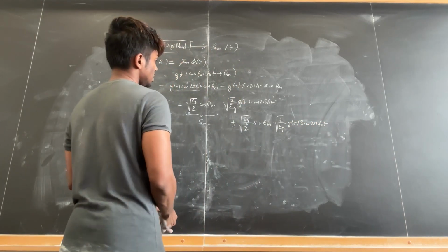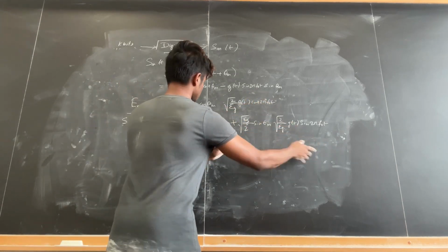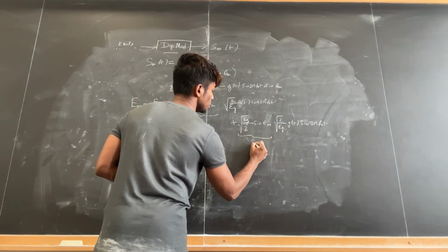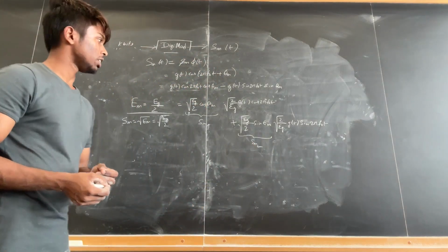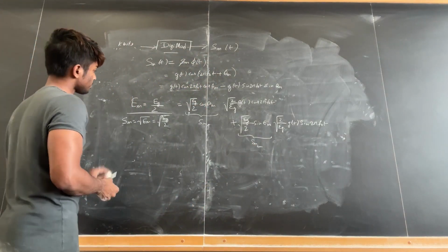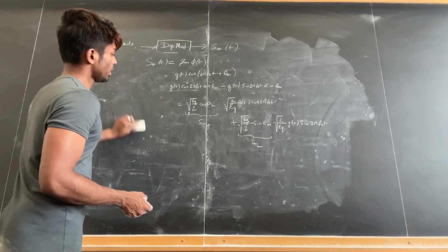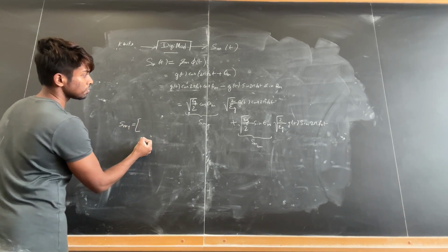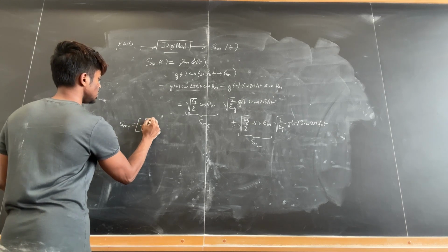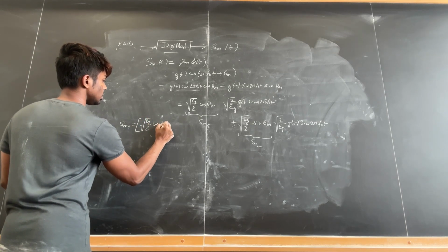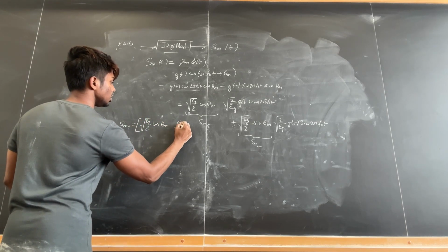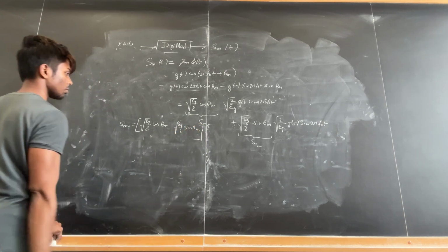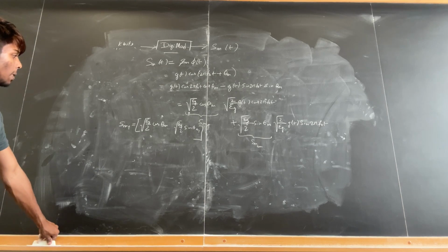Now we can easily see it is composed of two portions. So there is S_m1 and there is S_m2. So it is two-dimensional in its constellation diagram space. So we can say that S_m1 is a set of square root of E_g by 2 cos theta n and square root of E_g by 2 sin theta n, as it is two-dimensional.